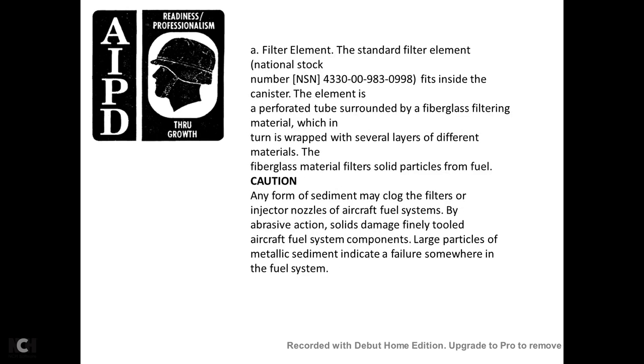A. The filter element. The standard filter element, national stock number 4330009830998, fits inside the canister. Perforated tubes surround the filter, which is fiberglass material turned and wrapped in several layers. The fiberglass material filters solid particles from the fuel.